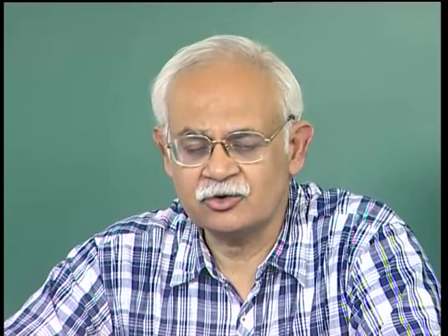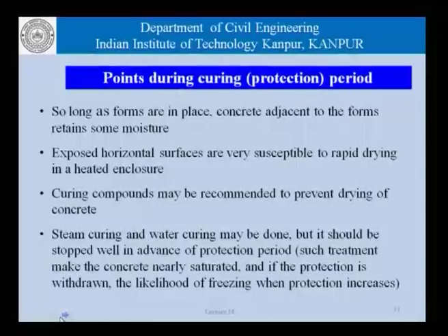The moment we remove the formwork, the concrete is obviously now exposed to ambient temperatures, and we need to ensure that the temperature drop that occurs within the first 24 hours after the formwork has been removed is in an acceptable range. Sudden cooling of the surface of concrete could be very, very detrimental from the point of view of strength development or the integrity of the surface concrete.